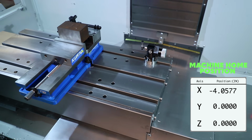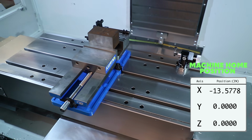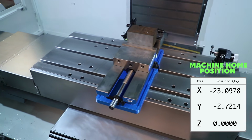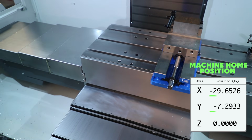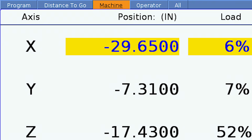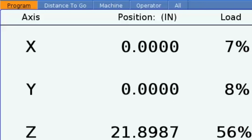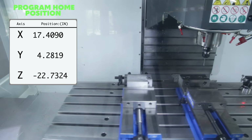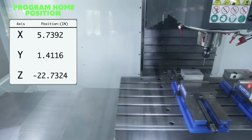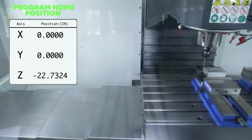As we saw earlier when we were using the machine coordinate system, as we move away from home position, the machine position display increases in the negative direction. But there's another useful position display. Now that we've defined where our part is with work coordinates, we can change to the program coordinates display, which treats our workpiece as our starting point. The control will show us our position relative to the workpiece.